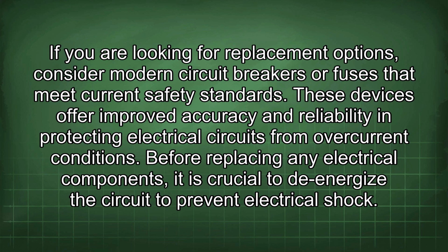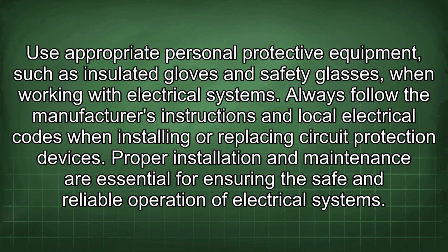Before replacing any electrical components, it is crucial to de-energize the circuit to prevent electrical shock. Use appropriate personal protective equipment, such as insulated gloves and safety glasses, when working with electrical systems. Always follow the manufacturer's instructions and local electrical codes when installing or replacing circuit protection devices. Proper installation and maintenance are essential for ensuring the safe and reliable operation of electrical systems.